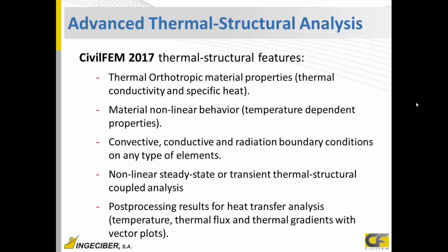The CivilFEM thermal structural features that we have are first about materials. We have thermal orthotropic material properties, that is, thermal conductivity and specific heat that are orthotropic. Also material nonlinear behavior, that is temperature-dependent properties: elasticity modulus, yielding stresses, and some other data are temperature-dependent. So we can perform a completely nonlinear analysis.